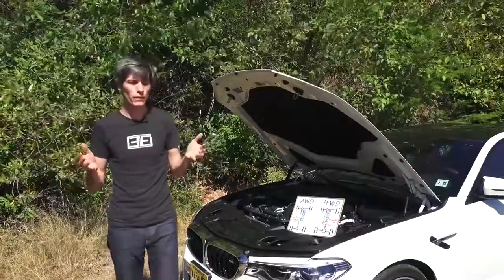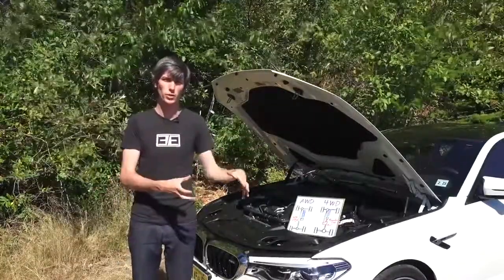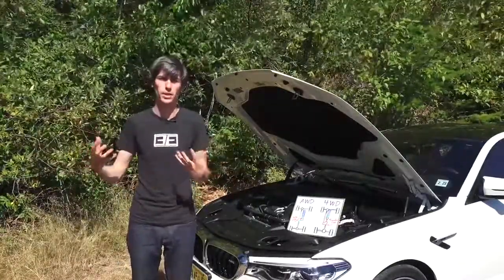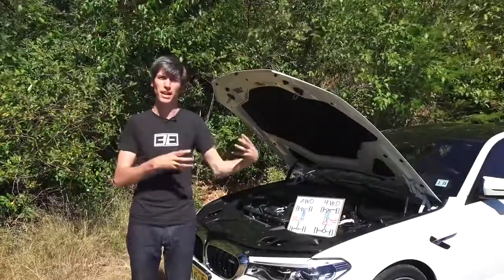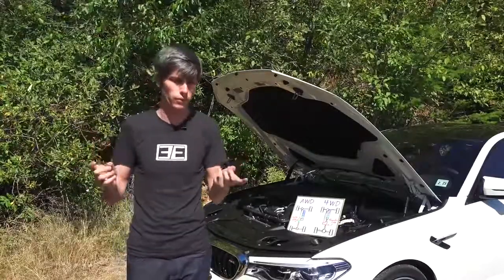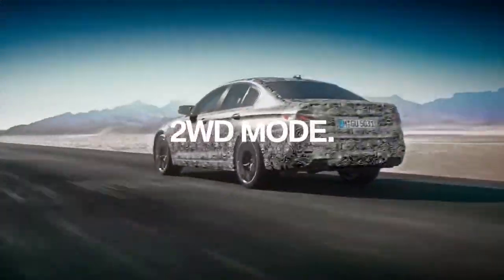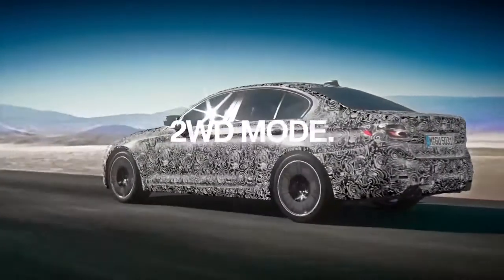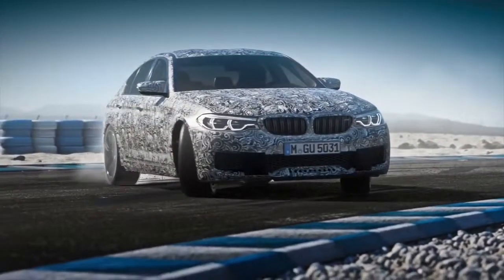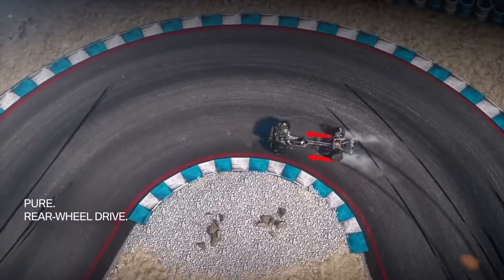Off-road, you don't have to worry as much about binding because the tire is just going to slip on the loose surface. Whether you're on dirt or rocks or things like that, the tire is going to end up slipping, not the drivetrain, so it's not as hard on the vehicle. The other advantage of the off-road system is that it's selectable between two-wheel drive. So you can choose as a driver, I only want to send power to the rear wheels, which, with this BMW for example, is fun to do because you can slide around and spin those rear tires. It's also more efficient to send power to just two tires rather than to all of them.